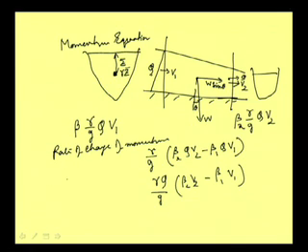So, this pressure force will be gamma into z1 bar, let me write. Here, suppose the depth up to the centroid is z2 bar. So, pressure will be gamma into z2 bar, and that is the average pressure. So, we are multiplying by the entire sectional area to get the force. So, the pressure is gamma z1 bar, multiplied by the area, and we will get the force.